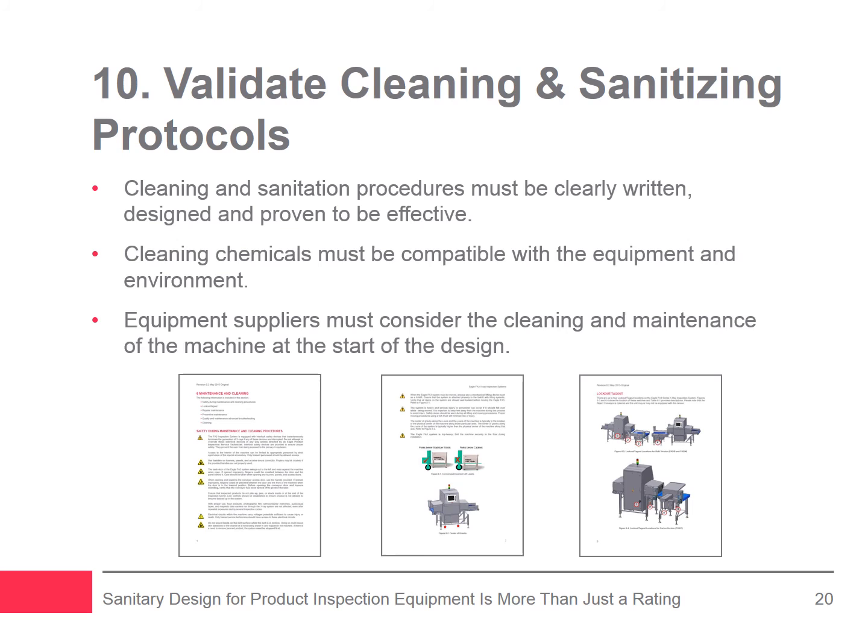not as an afterthought. Questions for meat processors to consider include: what needs to be cleaned and how? CIP or COP? Which cleaning process should be used, and are there restrictions on sensitive components? What cleaning and sanitation protocols are provided by the product inspection equipment supplier? What maintenance tasks are required after cleaning and sanitation?